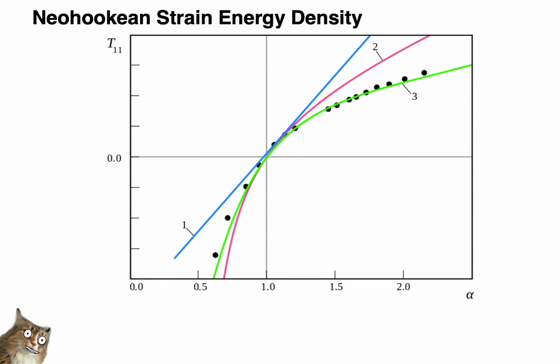One of the advantages of using a 3D reference space formulation for our cloth simulation is that we retain a 3x3 deformation gradient. This is because we are still mapping from a 3D reference space to a 3D world space. As a consequence, we can directly use standard strain energy density functions in our cloth simulation, like the Neo-Hookean energy we used for volumetric simulations in the 4th and 5th videos. For the simulation of cloth, we are going to introduce a different type of material model that is also very popular in computer graphics. But to do that, we are going to revisit the concept of deformation.